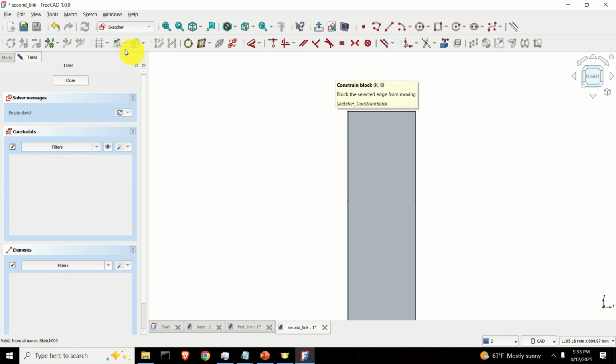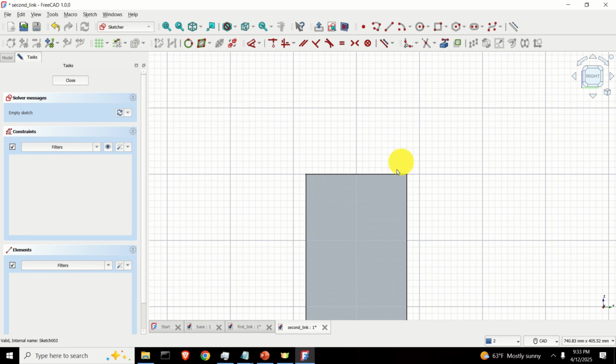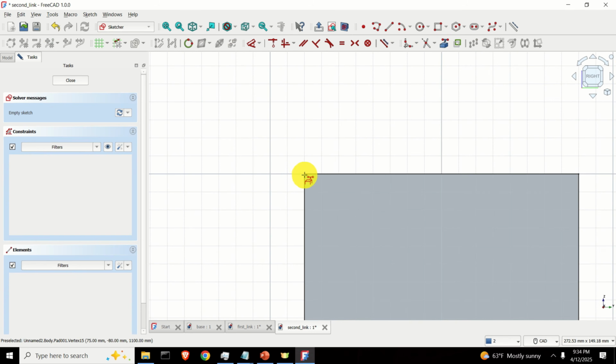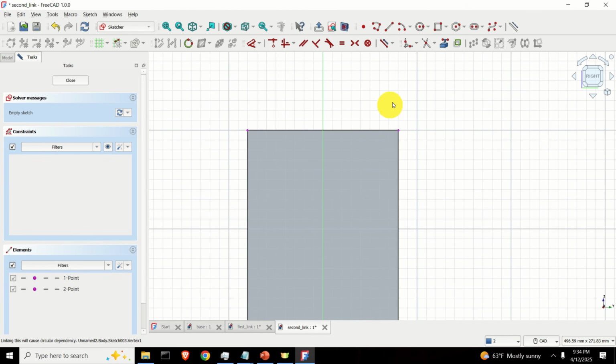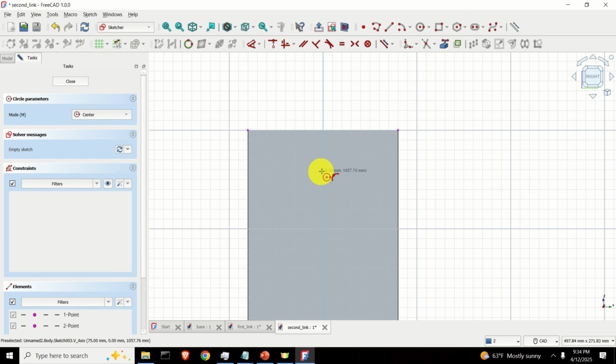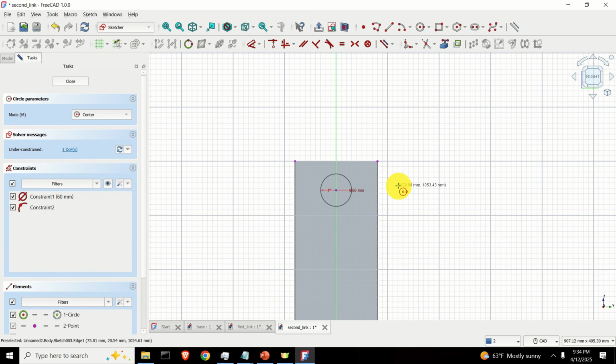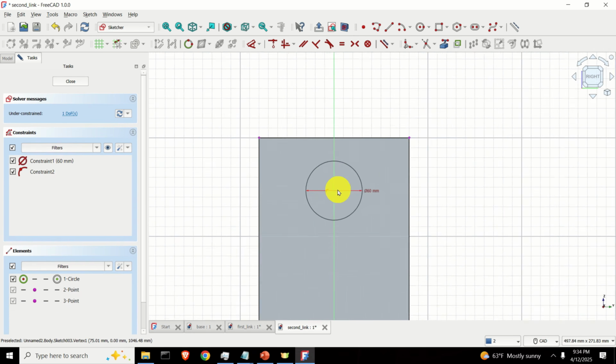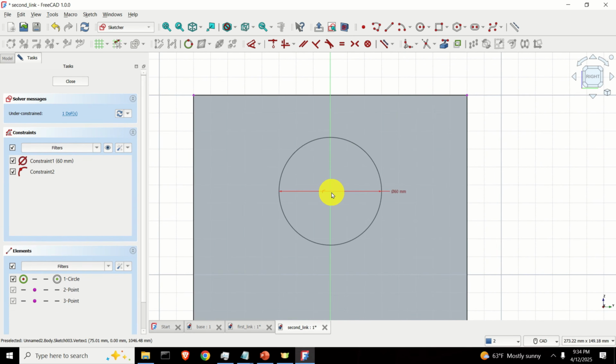To add the circle, turn on the grid, then let's again add some external geometry points. Click here, find this point over here and this point over here, do the right click, and let's create a circle. Click here. You can see that we're snapping to this line over here, and let's go with the diameter of, for example, 60. Okay, so here it is. Beautiful.